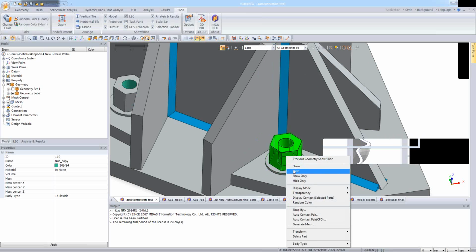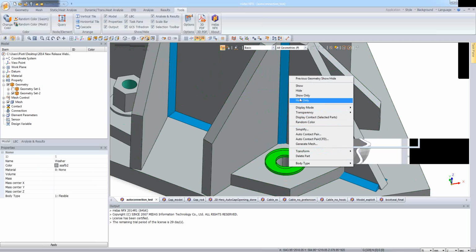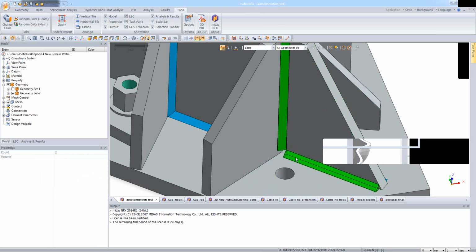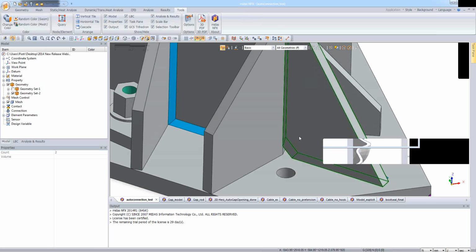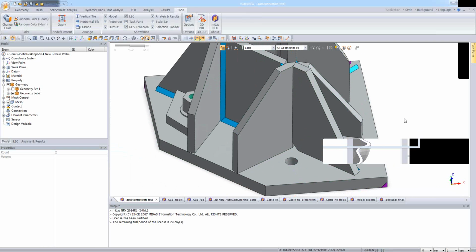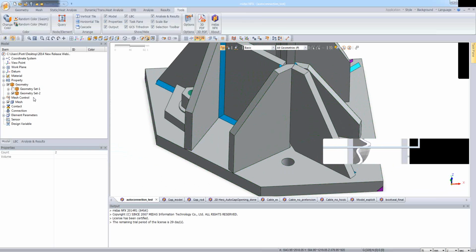If you want to do that, it will actually be a bit difficult, because you see I'm hiding the mesh and you don't have the imprint of this geometry on the other part. I'm hiding the joint as well. You see that you have no imprint on this model. So if you want to merge the nodes, it will be difficult, or you'll have to manually make the imprint on all the parts.